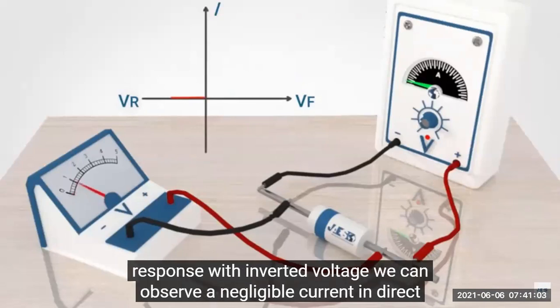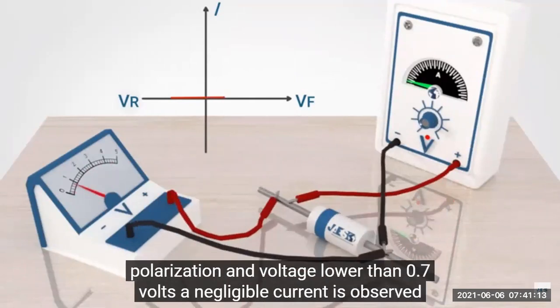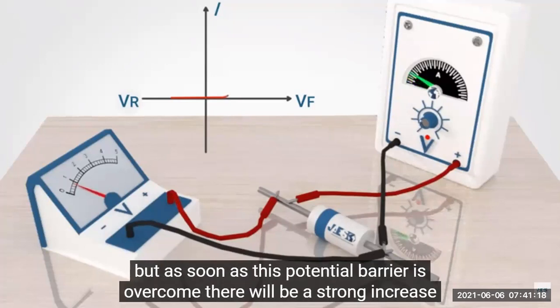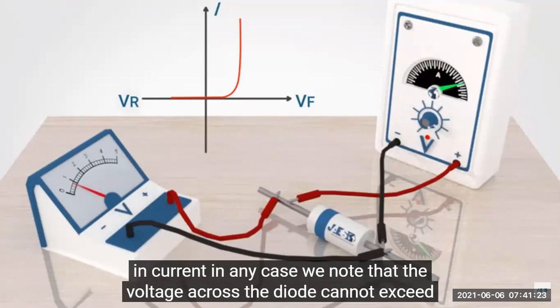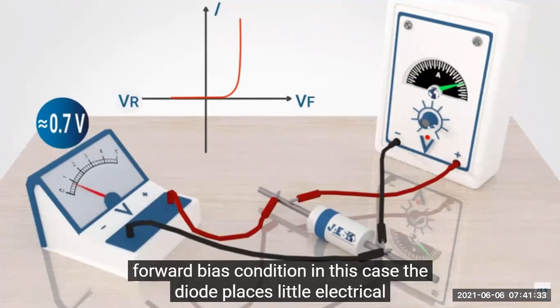With inverted voltage, we can observe a negligible current. In direct polarization and voltage lower than 0.7 volts, a negligible current is observed. But as soon as this potential barrier is overcome, there will be a strong increase in current. In any case, we note that the voltage across the diode cannot exceed 0.7 volts very much, even in the case of a high input voltage. This depends on the forward bias condition. In this case, the diode places little electrical resistance.